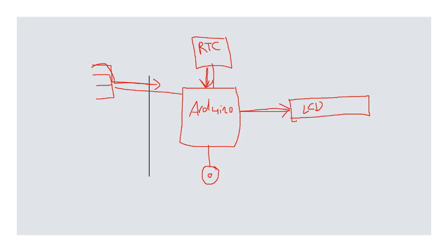Now, you can add a snooze feature for 10 minutes if you wish, and you can do a lot of things in the coding part. We are going to explain the coding part in more detail next, but for now what you need to know is that this advanced version of the automatic medicine reminder has 3 buttons for 3 modes: once a day, twice a day, and 3 times a day, and it uses the RTC module to take time and date data and provide this data to Arduino to select the time slots on which we want to take the medicine.